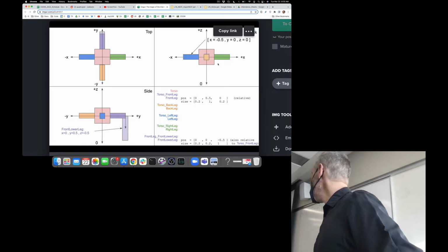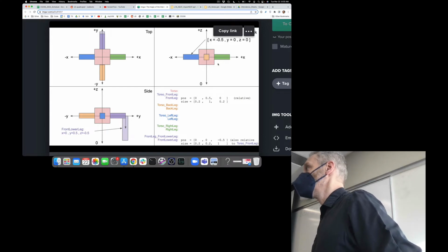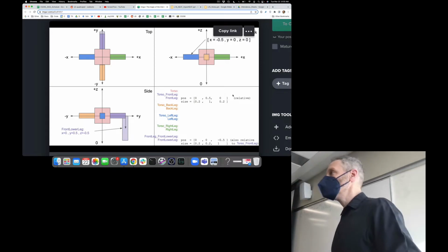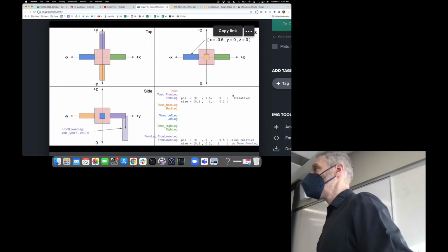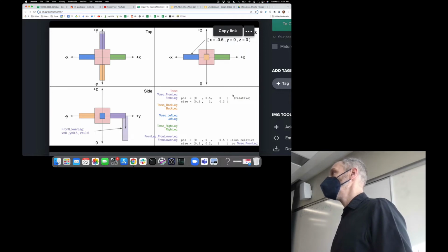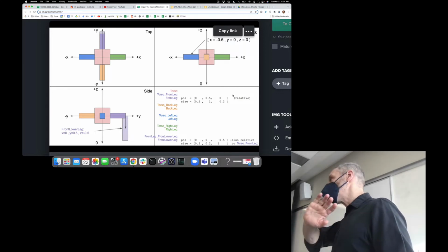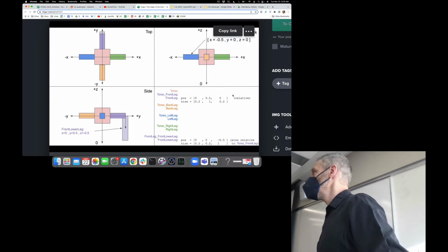As you build it up, you're going to strip it down to 3 links, because you already have 3 links, and then gradually build it up to 9 links and 8 joints. As you add each joint and each link, I would jot down on your engineering drawing the coordinates for each link and each joint, so you re-familiarize yourself with the combination of absolute and relative coordinates that are used in PyBullet. You could, of course, add everything in at once, cross your fingers and run it, but hopefully by now you'll get a sense that that's often not a good way to go.